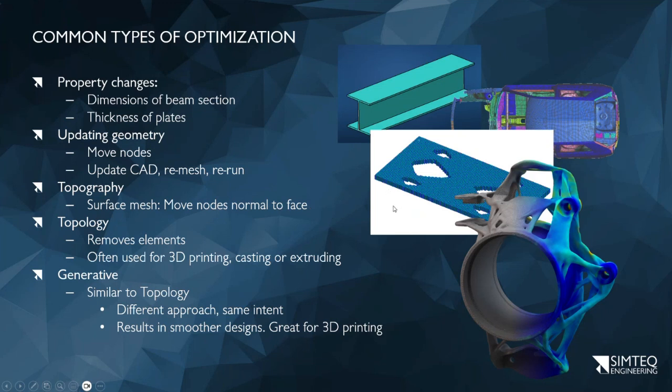In all of these cases, we still have the requirement of where do I want to end and what is an optimum design. So with 3D printing, it's purely material. Often for structures, if you add too many machining locations, it actually adds cost, even if in theory cost goes down. If I design something for aerospace, often we'll start with a pretty large piece of aluminium that we cut away a lot.